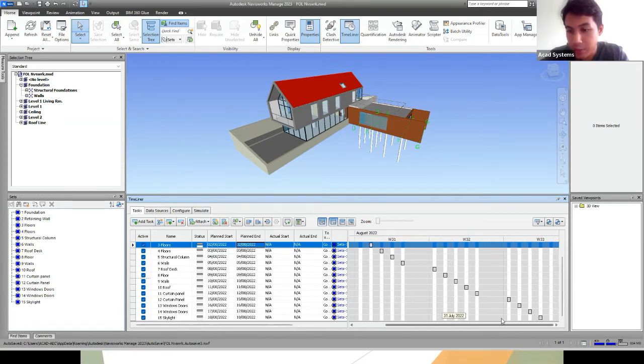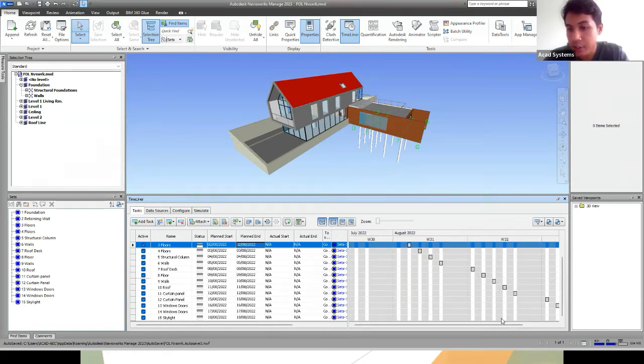This will show the graphics as in Gantt chart to our plan start and plan end here. Okay, for this time we don't input the actual end and actual start, so it doesn't show in the Gantt chart. But if you have it, you can also have it in your Gantt chart.